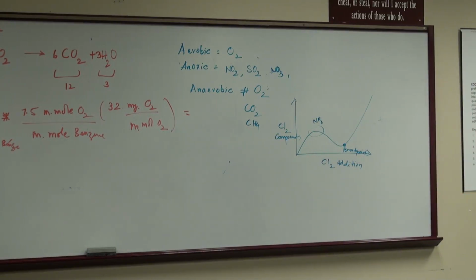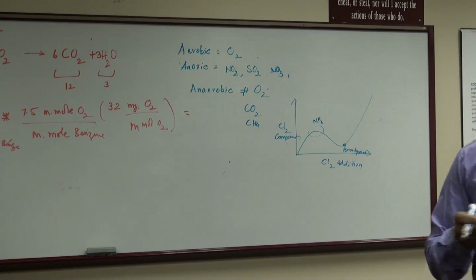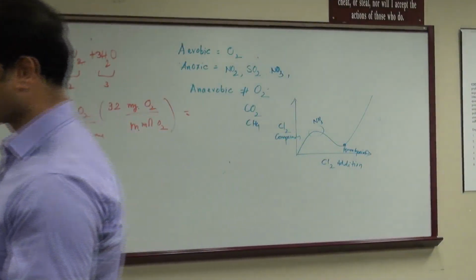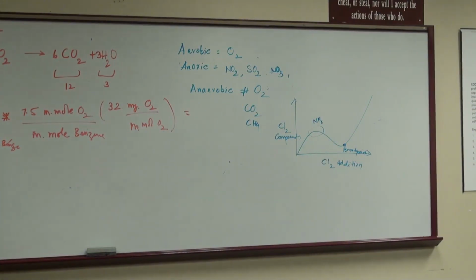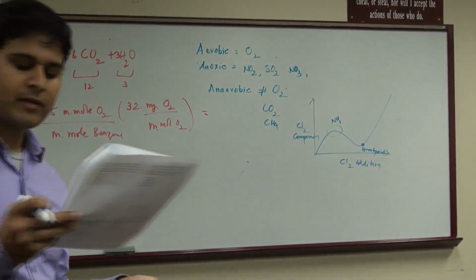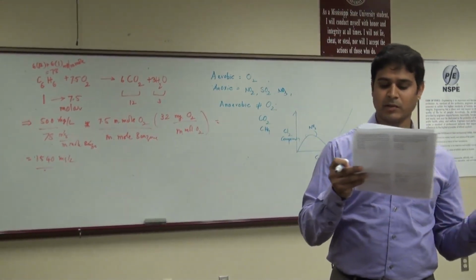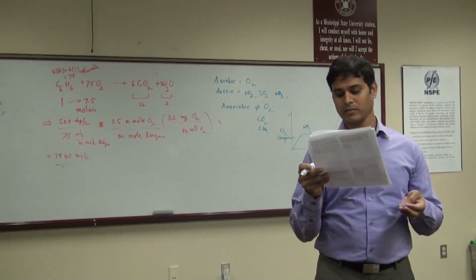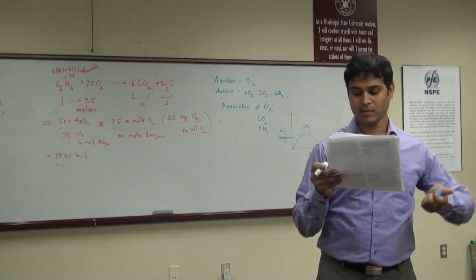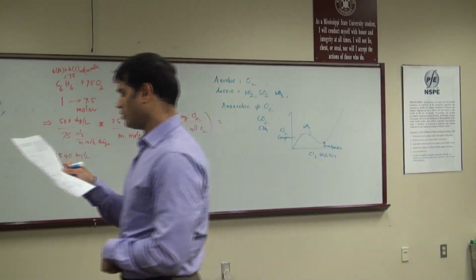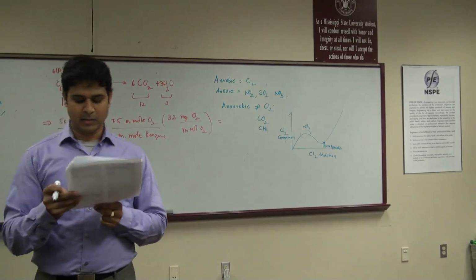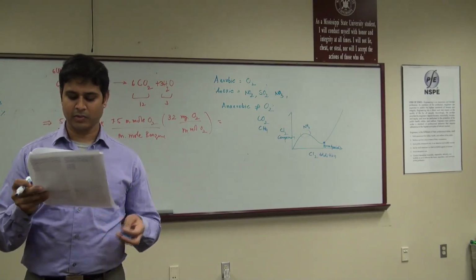One last thing we'll see, and then we'll do some problems. Also, I think that's another interesting one. The presence of heavy metals. The next question: the presence of heavy metals in dewatered wastewater sludge would cause the following concern: A, poor dewatering characteristics leading to wet sludge. B, chemical reactions between the heavy metals and the soil. C, binding excess water in the soil during winter months. And D, elimination of land application as a viable disposal alternative.